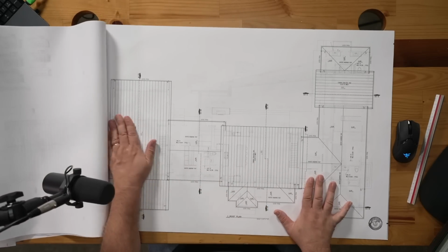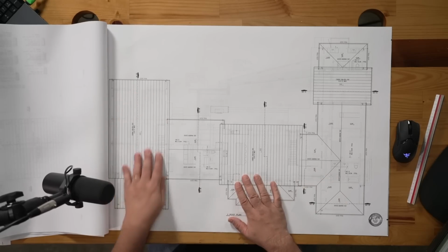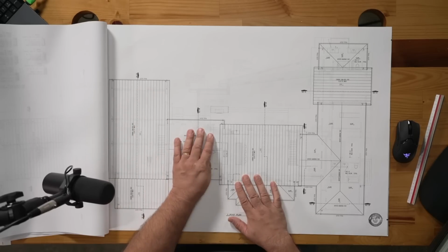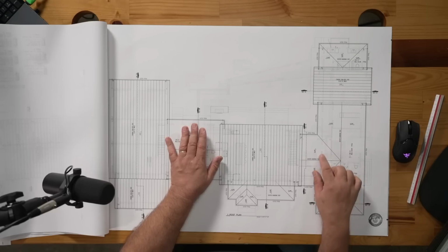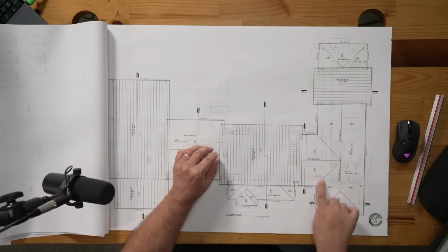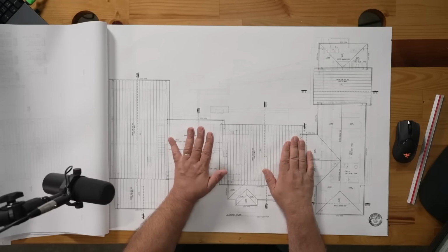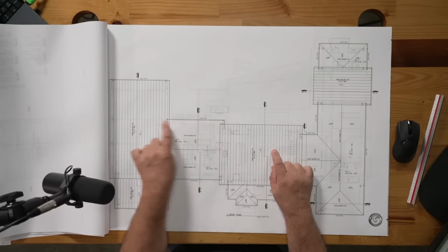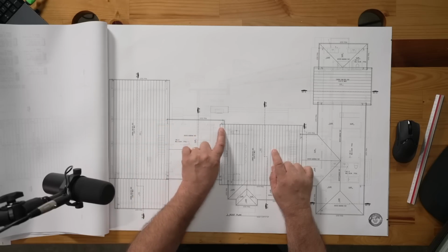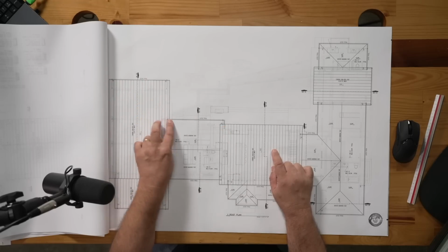This is the roof plan. On the roof plan, you notice it shows where we have the standing seam metal and where we have the flat roof. It's a tapered membrane roof, so we'll have tapered insulation, so you can see where the high points and the valleys are, where I'm intentionally showing the slopes. You can also notice I put where the gutters are going to go and where the downspout locations are, where they breach the roof and where they are on the wall. So I have that all preliminarily laid out.